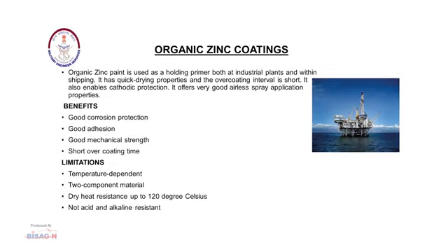Organic zinc paint is used as a holding primer both at industrial plants and within shipping. It has quick drying properties and the overcoating interval is relatively short. It also enables cathodic protection. It offers very good airless spray application properties.